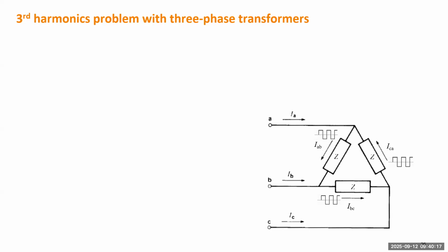If you do the Fourier transform, how many harmonics do we have for the square wave? If it's a rectangular or square wave, each half cycle is basically perfectly symmetric. So if we do the Fourier transform, definitely you have omega, the fundamental frequency, and the next ones will be third, fifth, seventh, ninth, and so on. But you only have odd order harmonics. You don't have even harmonics.